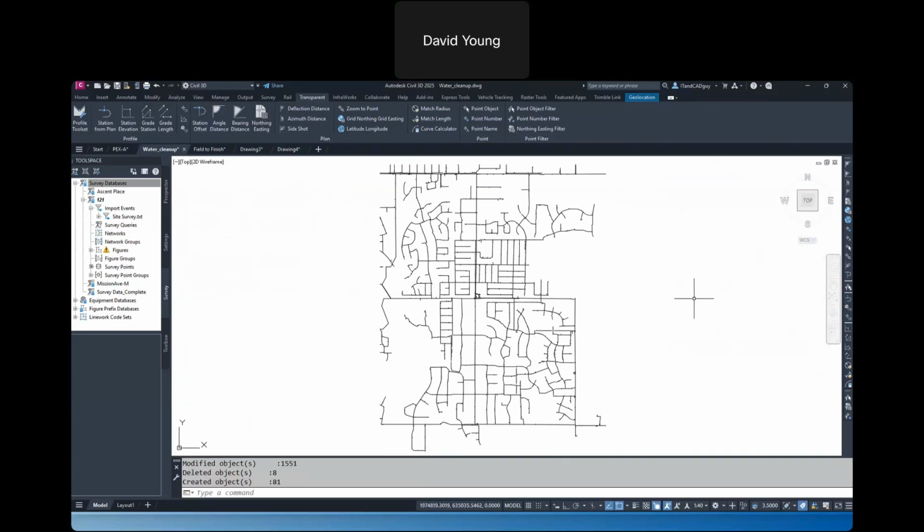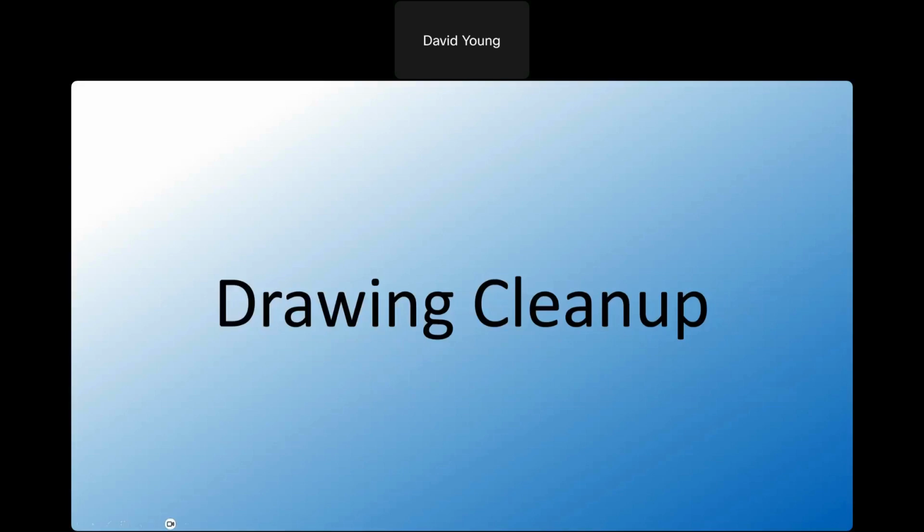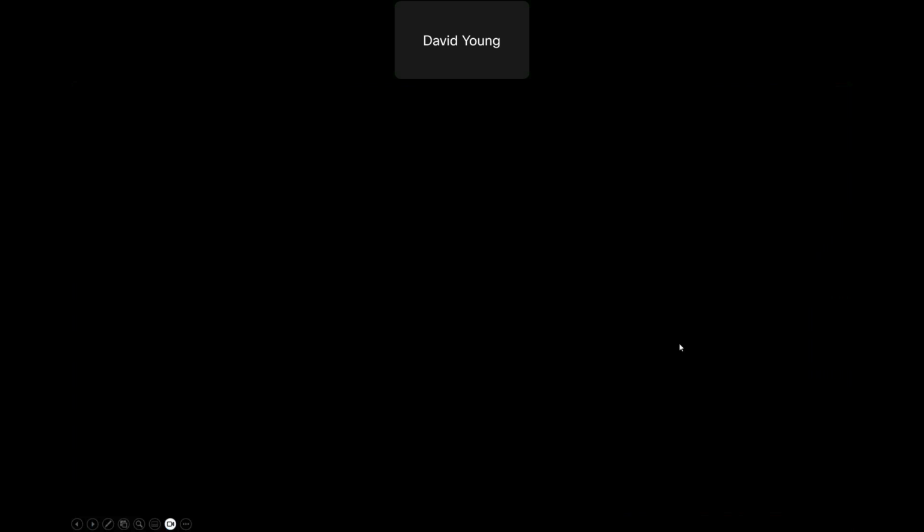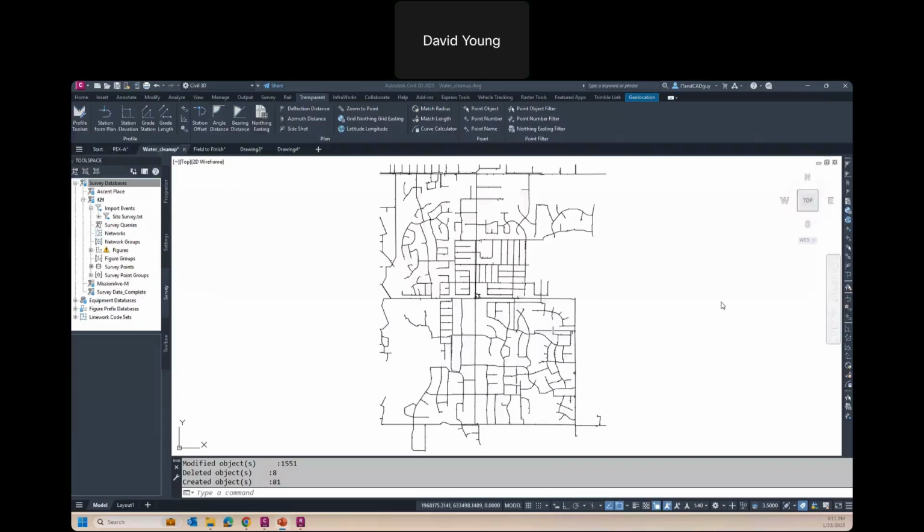All right. You know what? I think that is about it that I said I was going to show you. Yep, it is. Into my slideshow. So it wasn't quite a full hour, only about 40 minutes or so, but a lot of simple tools that you can use in Civil 3D that you don't have in AutoCAD. Right? Even if it's just using an alignment instead of a polyline for a center line of something. The fact that you can just move a grip and the curves go with it is way more powerful than regular AutoCAD.